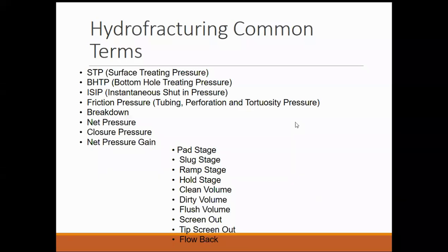Clean volume is the volume of the frac fluid. When it is mixed with sand, it is called a dirty volume. What is the flush volume? It is how much flush volume you have to pump to flush the entire wellbore sand into the formation. Okay, so that is called the flush volume.